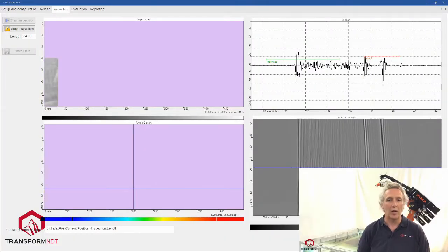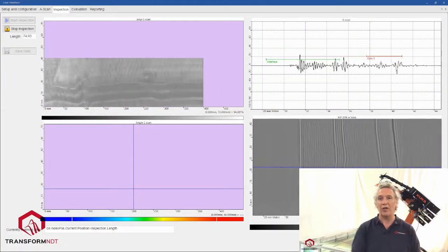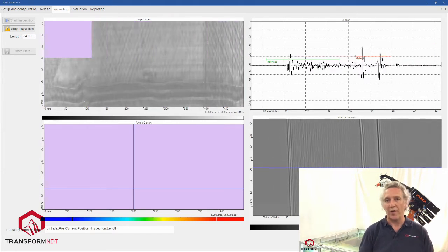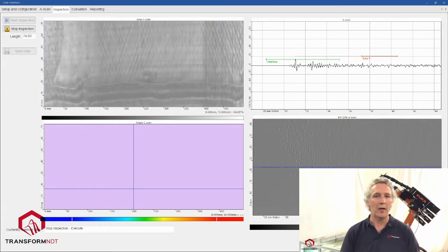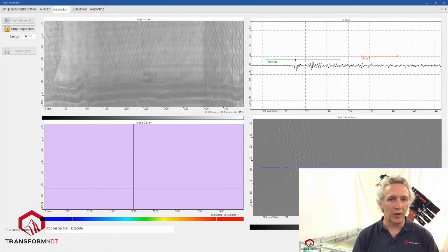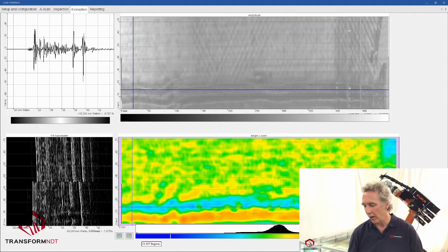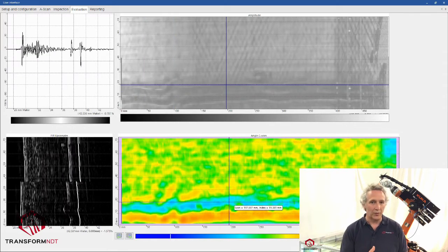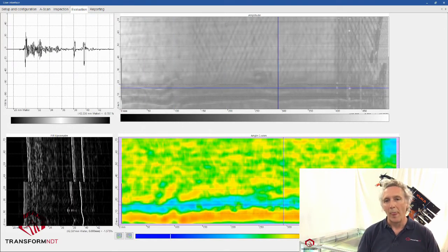So this is quite exciting, just to show you what you get if you go for a little bit more severe waviness. This is actually showing up on the C scan, but even using that data, you can't really get an assessment of severity. You just know there's a wrinkle there. And again, a couple of seconds later, we get the angle data, and then if we analyze that in a little bit more detail, you can again see the wrinkles.